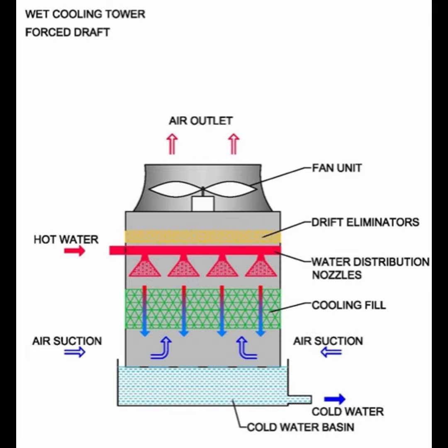Heat transfer. As the hot water trickles down over the cooling fill, it comes into direct contact with the incoming cooler, drier air. A small portion of the water evaporates, taking latent heat from the remaining bulk water. This evaporative cooling is the primary mechanism of heat rejection.